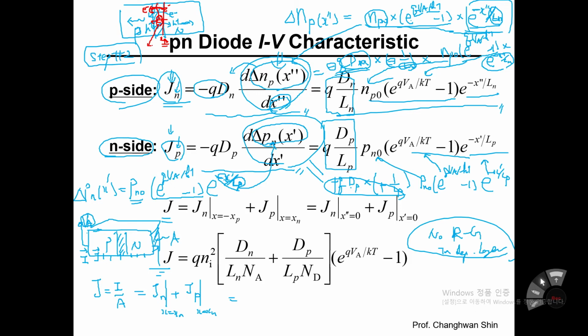Well, definitely in the depletion layer there is a built-in electric field from N to P side. So electrons would experience being pulled back because of the electrostatic force coming from the built-in electric field. However, the diffusion force is still strong, even much stronger than the drift force. So that's the reason why electrons can be injected into the P side for a given forward bias.